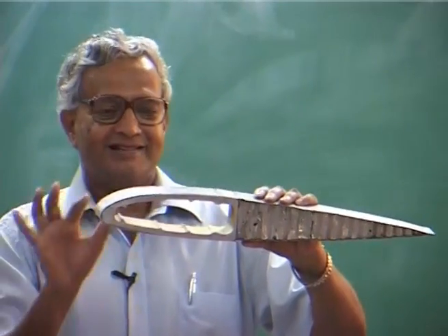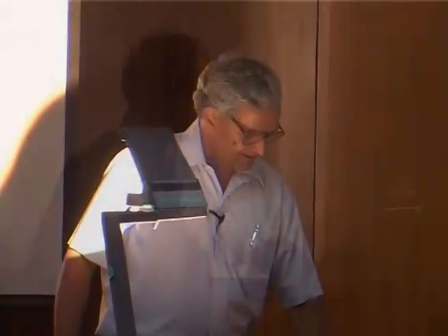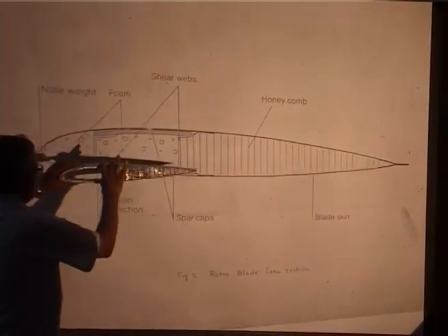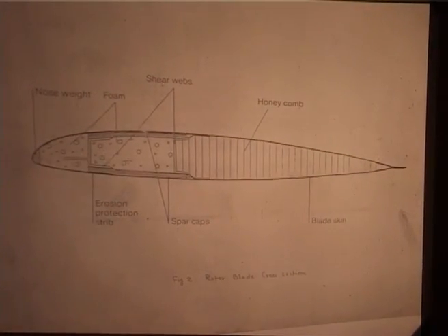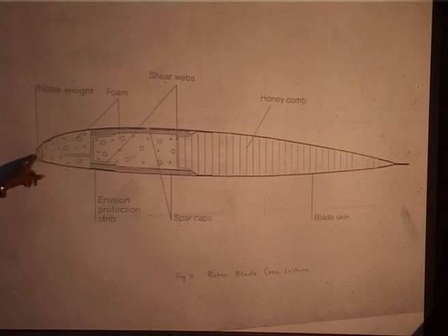So, this whole design is made in such a way that, I will show a typical section of a rotor blade, just similar to this. Only thing is each blade has its own section. This is the real life actual blade cross section. You always put a leading edge weight, that is to shift the center of mass to 25% chord from aeroelastic considerations. Okay, we will learn that.